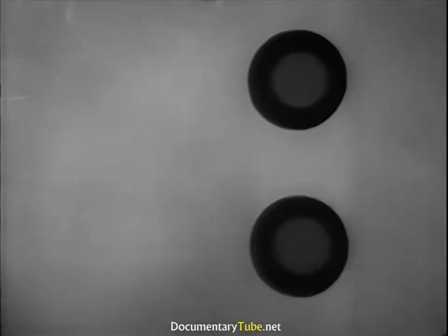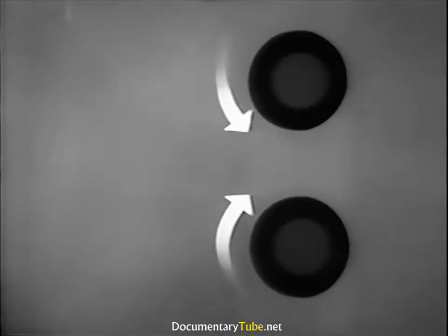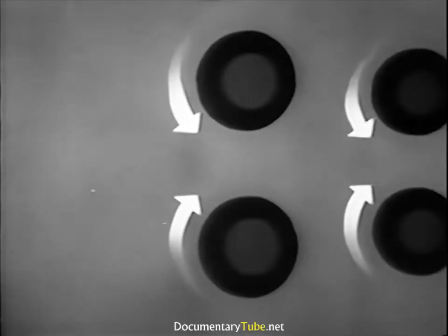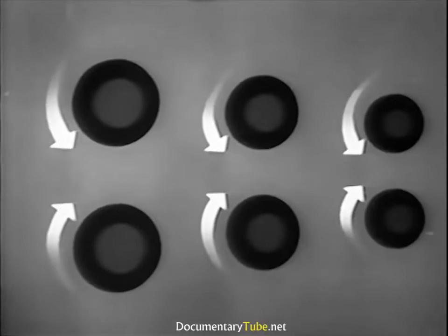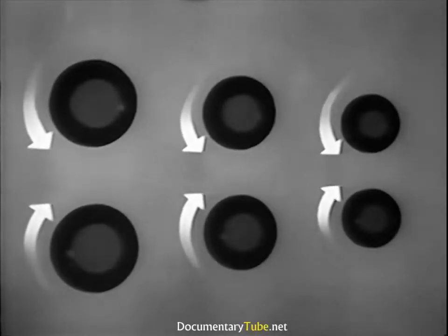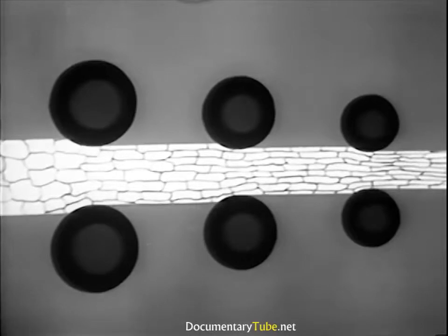A pair of oppositely driven cylindrical rolls is the mechanical basis of the cold rolling process. A series of such pairs of rolls is used, the roll opening of each pair becoming progressively smaller. The passage of the ingot through successive pairs of rolls reduces the thickness of the metal. In the process of cold rolling, the equiax grains are flattened and elongated.